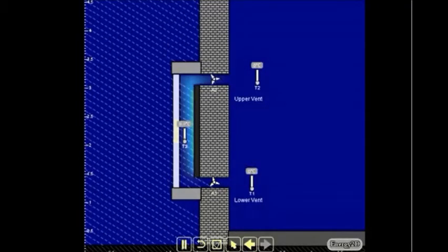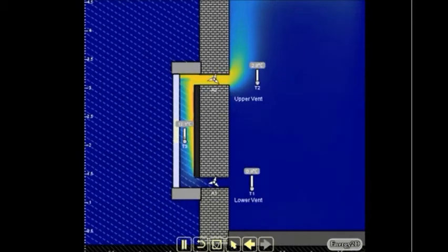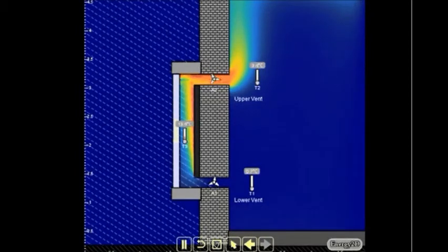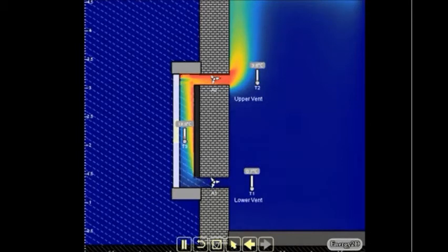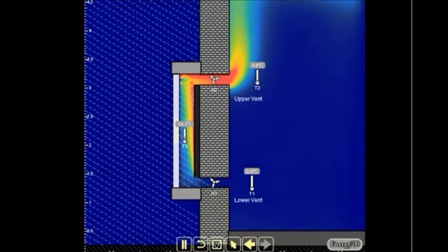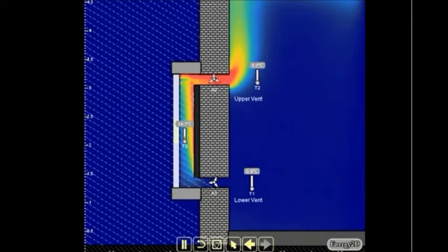A trombe wall is simply a construction of 2 materials that is placed on the south facade. From the outside, a trombe wall looks like an inoperable window that is closed by a wall behind it, or a very narrow greenhouse. The glazing has to be single glaze in order to absorb the most amount of solar radiation that hits it. On average, the gap between the glazing and the back wall is about 5 to 30 centimeters. The more it goes, the less effective it can get.